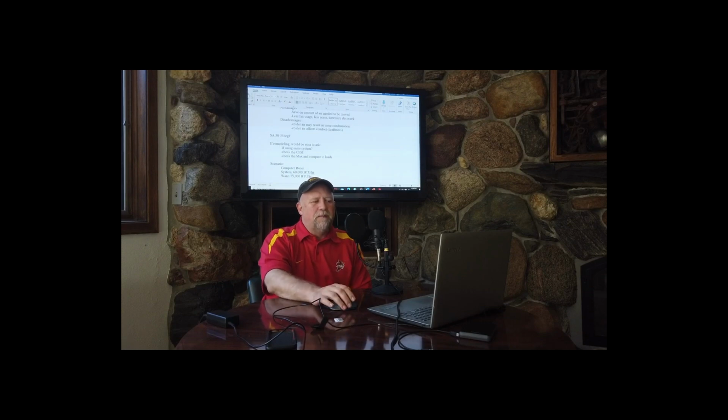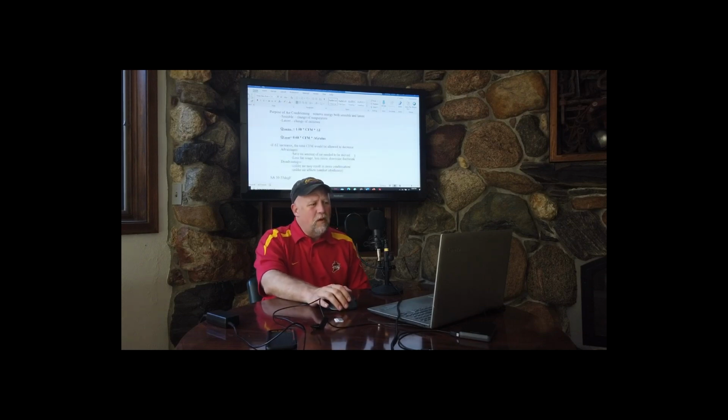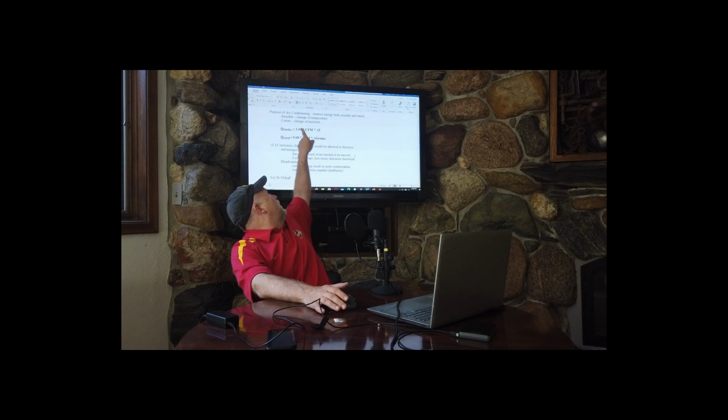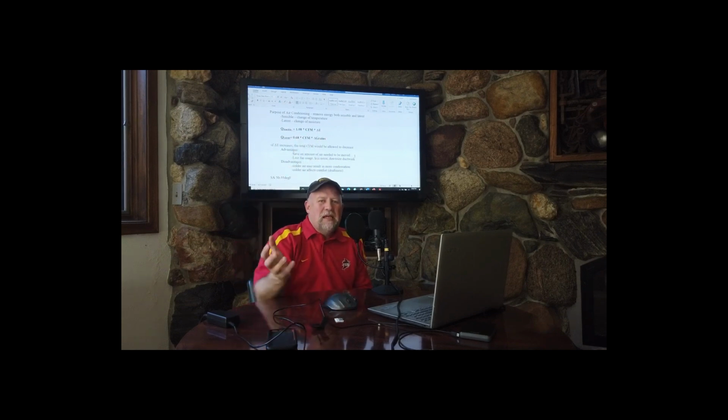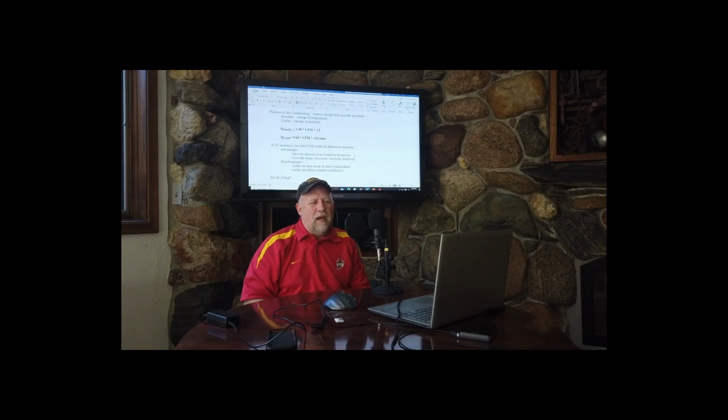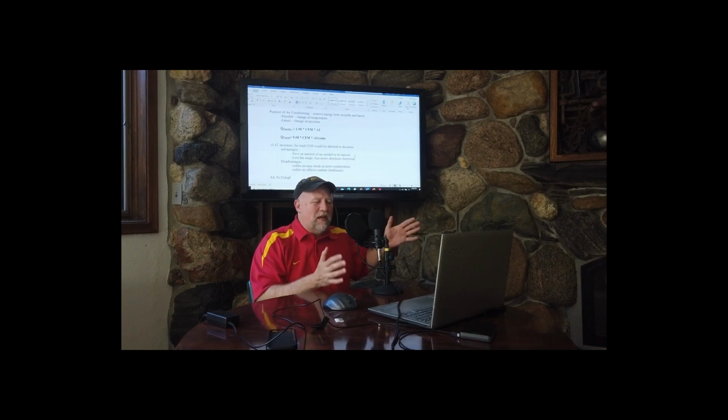Now, something to keep in mind. We can use this equation, this 1.08 CFM delta T. As an engineer, I can use that in a couple of ways. If this was an existing building and I wanted to know, well, what is the maximum cooling capacity? In other words, what's the maximum amount of heat production in a room I could have?